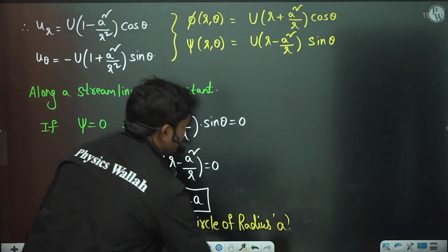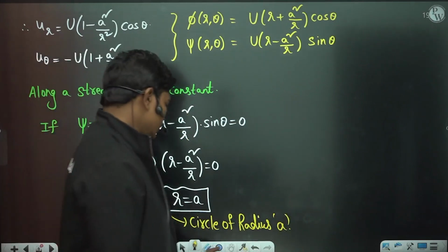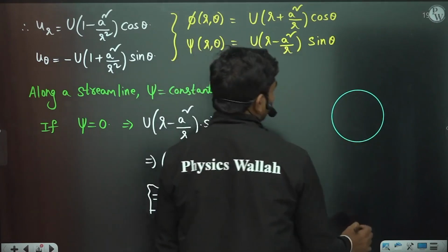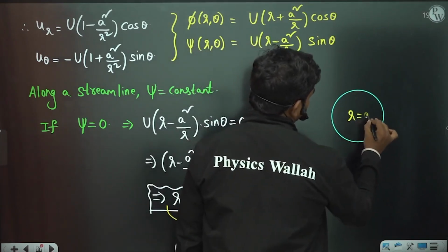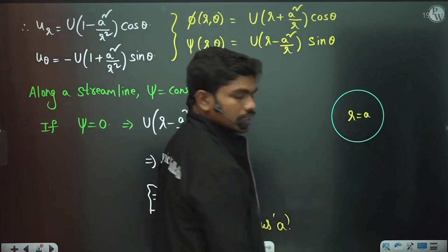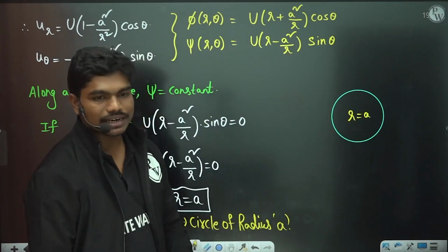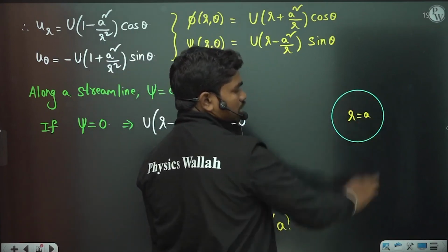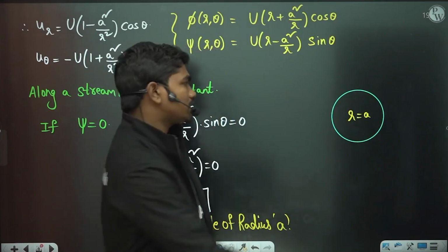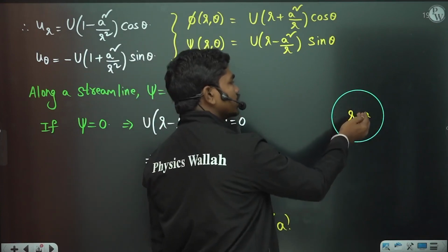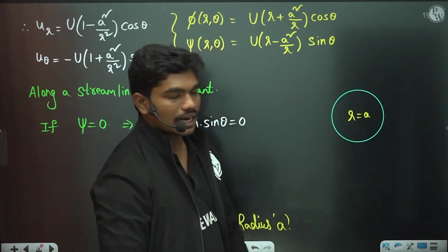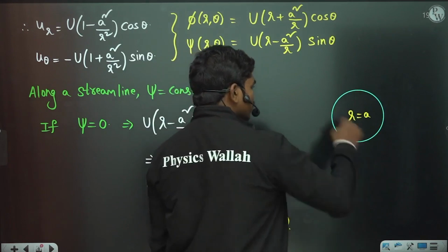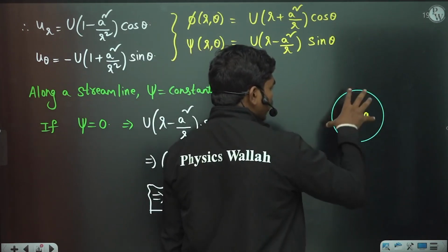Now try to understand one thing. One streamline is something like this. This is a streamline, r is equal to a. It's a closed streamline. Whenever this streamline denotes a circle, practically flow cannot enter the streamline. There cannot be any flow across the streamlines. There can be some flow inside, but the inside flow cannot come out either. So since flow cannot practically enter this, whatever flow is coming should travel only on the outside; it cannot enter inside.